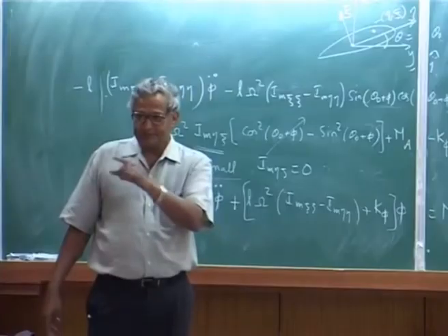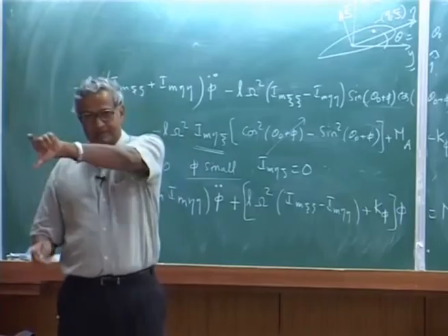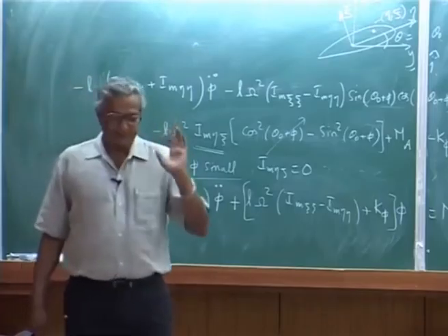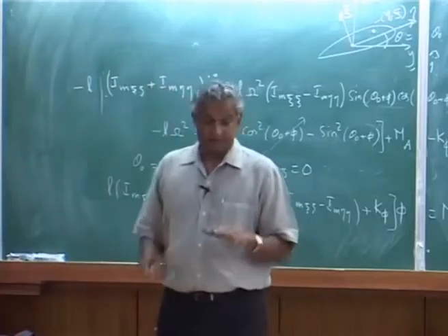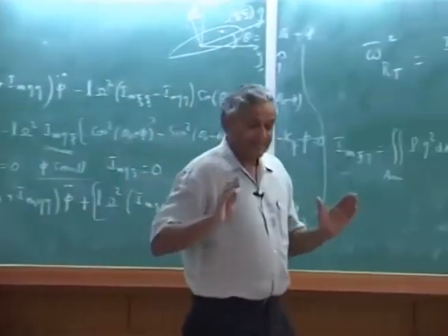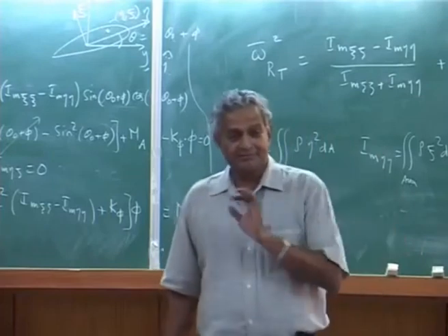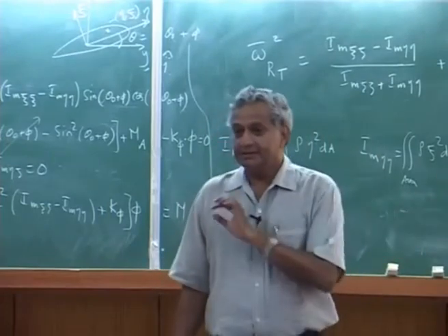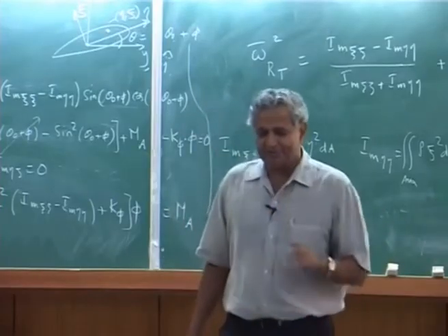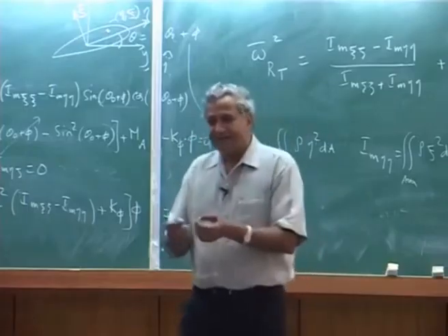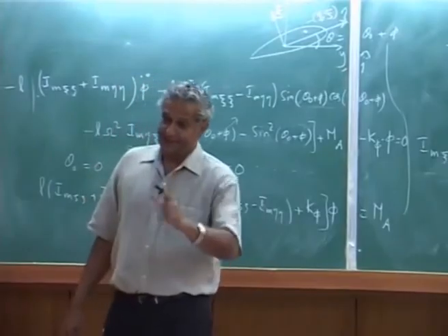And if aerodynamics is ahead of the feathering axis, lift will twist the pitch angle. You can have some kind of a divergence type of problem which is there in the fixed wing, you will start having. So, here the blade is designed such that mass center 25% chord, elastic axis at 25%, but exactly 25, no, if it comes to 24.5, 8, 9, it is okay, take it. Yes, elastic axis of the cross section is also at 25%.